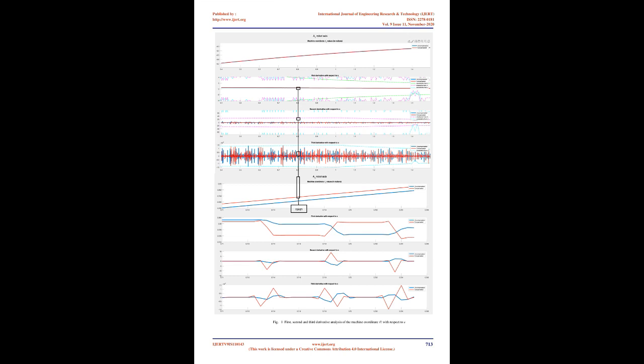Max IA, Max IJ. Similarly, the second derivative of the functions with respect to the total vector displacement of the robot axis has to satisfy the following two constraints, raised out of acceleration and jerk limitations respectively, for each robot axis. The third derivative of the functions with respect to the total vector displacement of the robot axis has to satisfy one constraint, raised out of jerk limitations, for each robot axis.